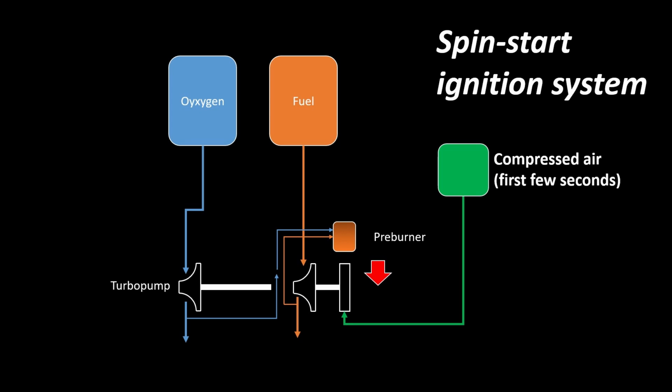At the beginning, I mentioned there would be two ways to start the turbopumps. One way is igniting the preburners with a different fluid like TEA-TEB, and the other one is what the Raptor does. The Raptor engine doesn't ignite the preburners before the turbopumps, but instead it works pretty much the other way around. It starts the turbopumps before the preburners ignite, so that the preburners don't burn anything else than methane and oxygen. This mechanism is also sometimes referred to as the turbopump spin start.